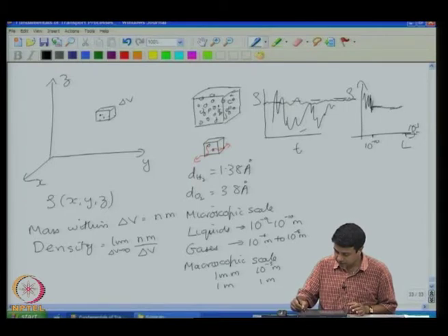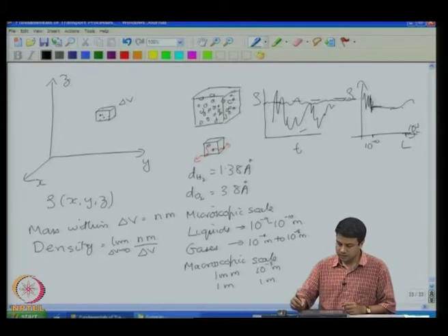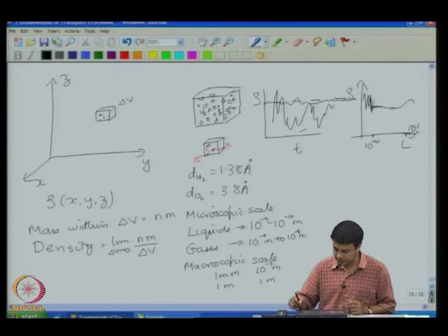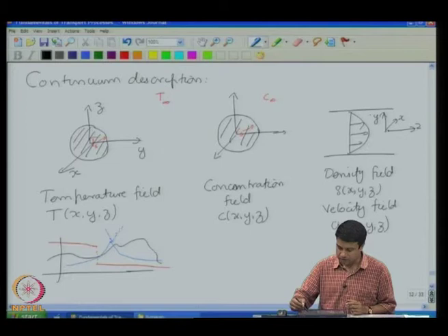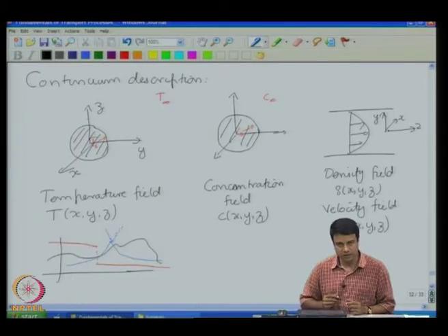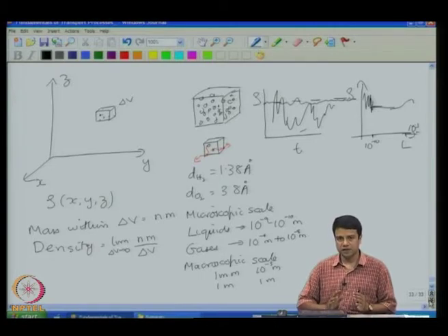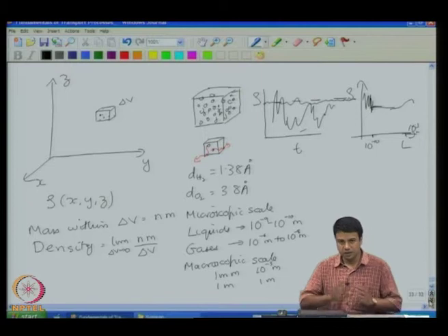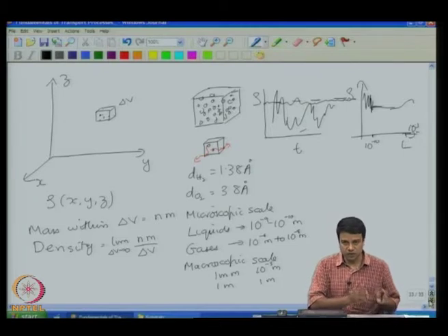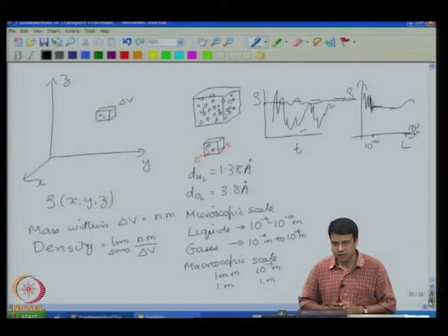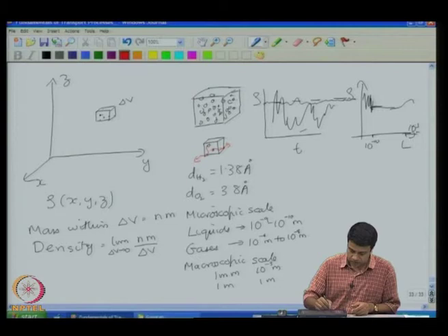Then as it becomes still larger, I will start getting variations again, because I am actually averaging over real concentration variations within the system. Okay. I am actually averaging over density differences across the pipe or over length scales comparable to the radius of the catalyst particle. Okay. So, this microscopic volume is defined in such a way that it is large compared to the molecular size, but still small compared to the macroscopic scales. The definition of this requires that I have a sufficient range of length scales between the microscopic scale on the one side and the macroscopic scale on the other side, such that I can find scales in between, which are large compared to molecular size or mean free path, but still small compared to the macroscopic scale. Okay. Over that volume I can do this definition of density.